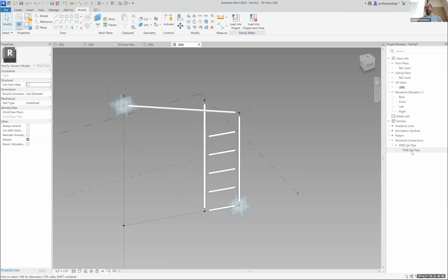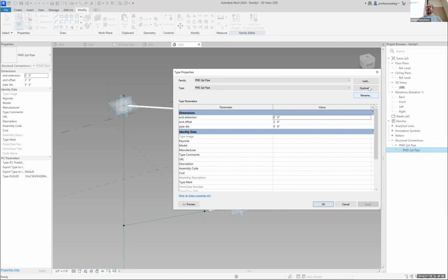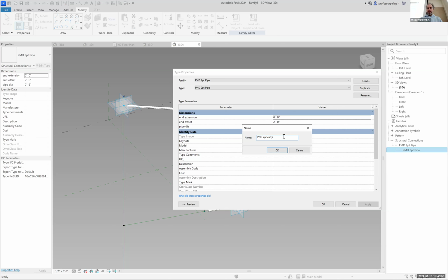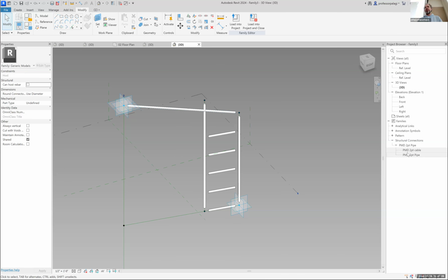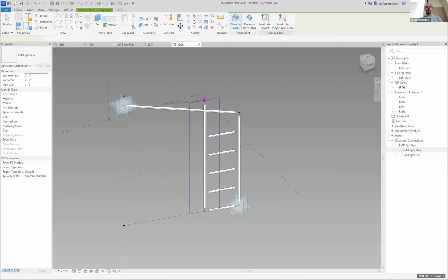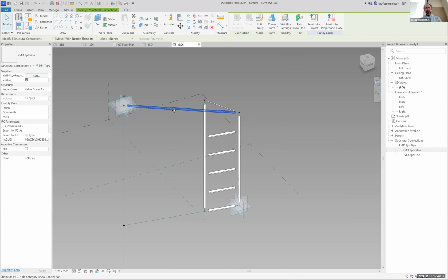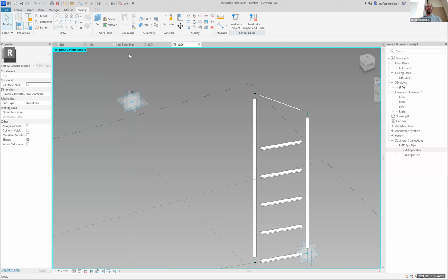Now I'm going to double click on this and say duplicate and then say cable. Oh, shit. And diameter 2 inches. Okay. Now I want to find a node. Like I know my cable is going to go from here to here, but I want to have a node here. So I'm going to take this HH. Oh, I don't have a reference line there. I need to put a reference line in so I can mark a spot that I want.